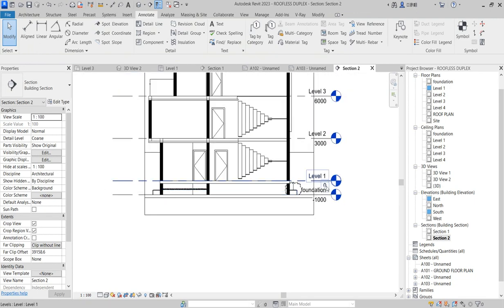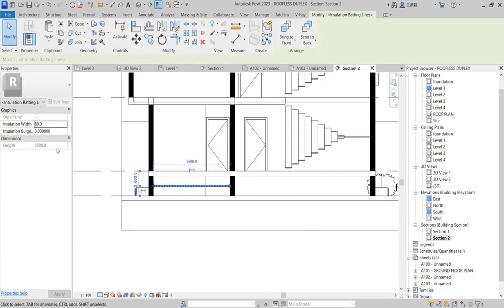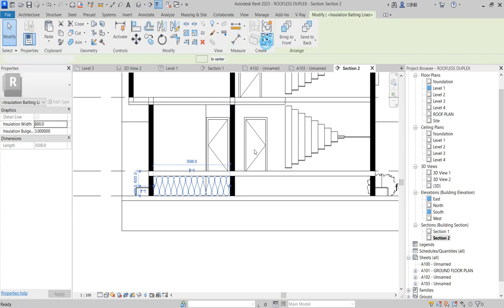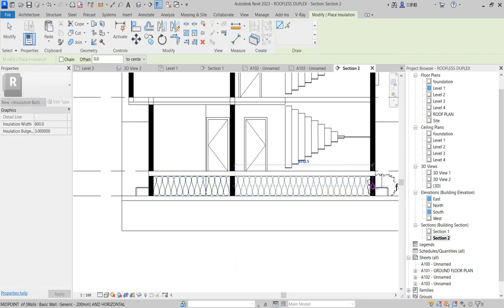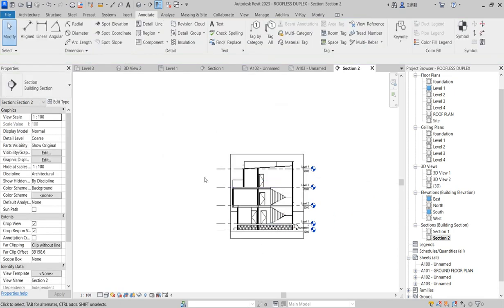So like this one now is 800 from this slab. So I'm going to select this one and change it from the property, and I will say 800 instead of 80. Can you see it's big? So you select that and say create similar. At the create similar, you create the same thing, and it's done.